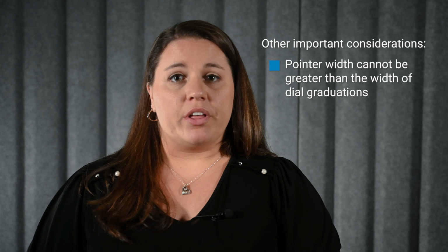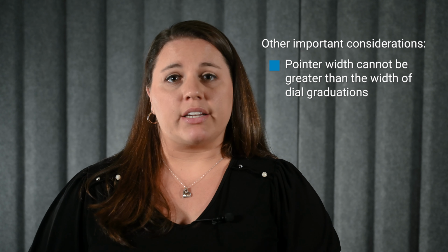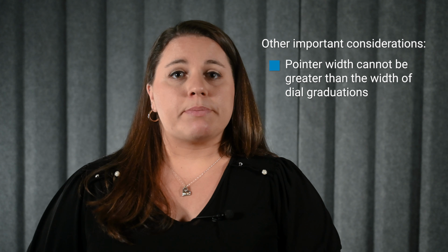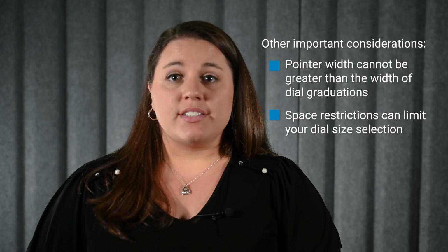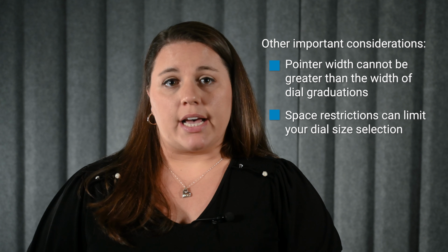Some other important considerations are pointer width. Pointer width cannot be greater than the width of the dial graduations and may be a limiting factor when determining how many graduations are available with corresponding dial sizes. Space restrictions. If there is not a lot of space where the gauge will be installed, you may also be limited in your dial size selection.